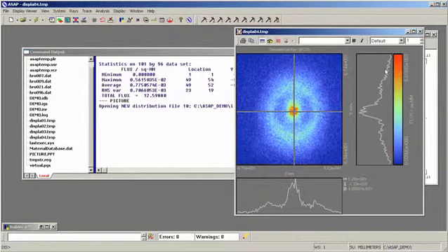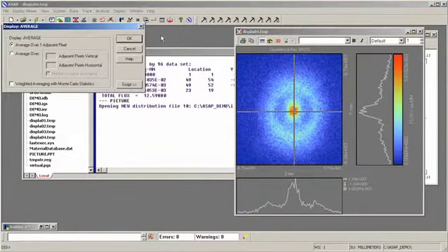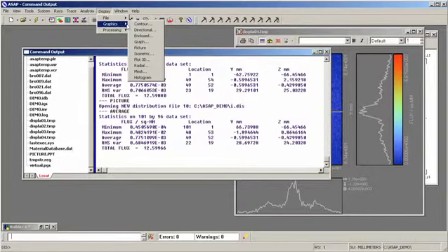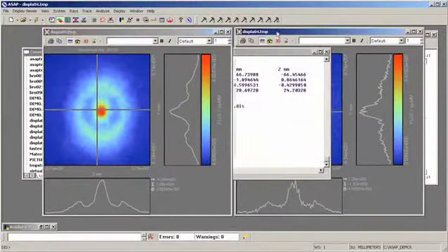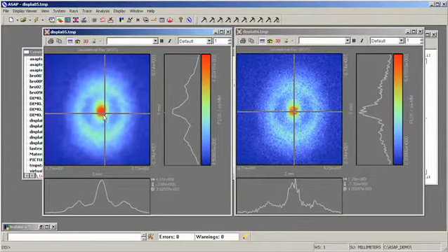Another option is just to average out some of the noise in the display menu. Under processing we have an average option. I'll use the defaults. Click OK, and next we go back into display graphics and generate the new picture. So here's the averaged result, here's the unaveraged result. We see that it's significantly smoother if we do a little averaging here, and that's basically it.